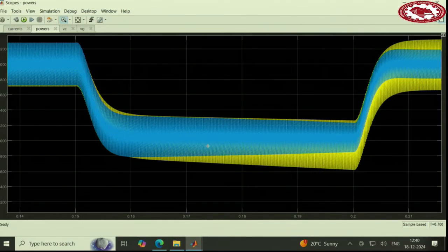But in AC we know how much inertia synchronous generators provide, so we can really mimic them by the inverter exactly. So we designed the capacitor or emulated capacitor in AC to give us the same amount of inertia, or more if we want, that a synchronous generator provides.